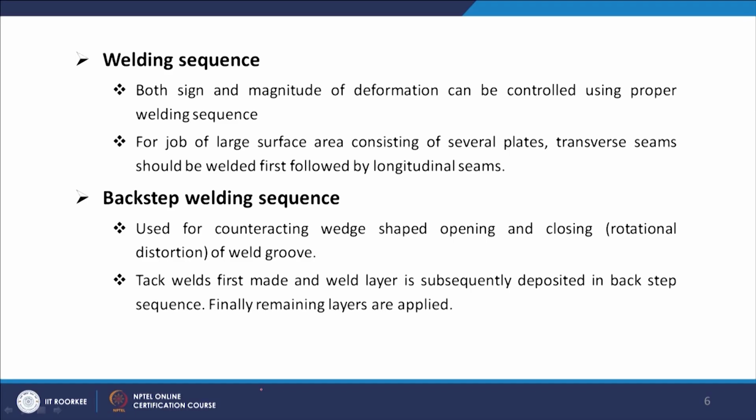That is for that kind of structure. Then, when we are dealing with the welding of I or H beam sections, first to be welded are the joints within each web plate and the flange, and then we do the butt joint between the web plate and flanges of the beam. So, that is what we do for I and H section beams.